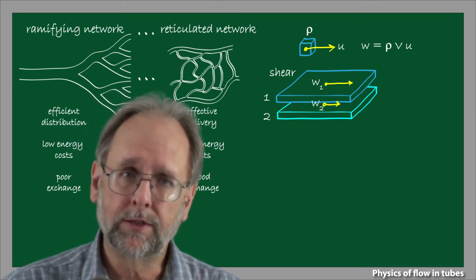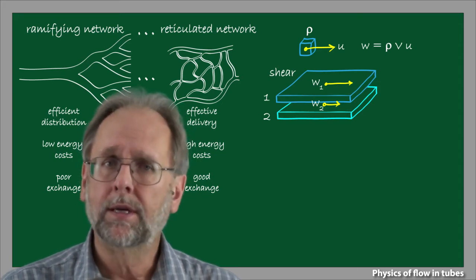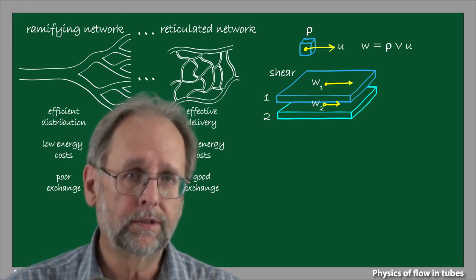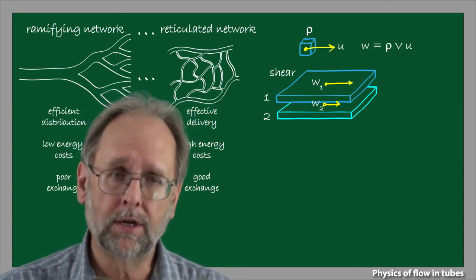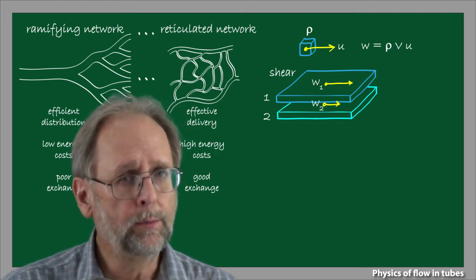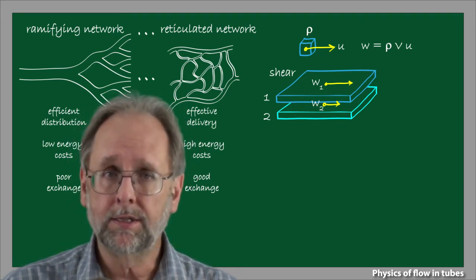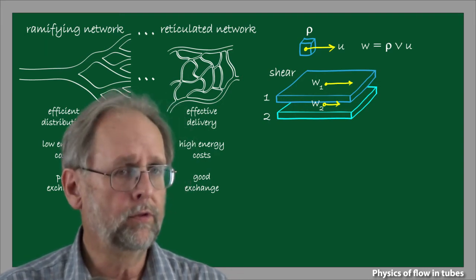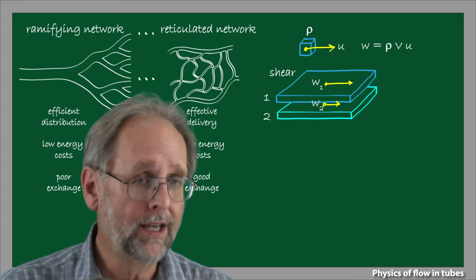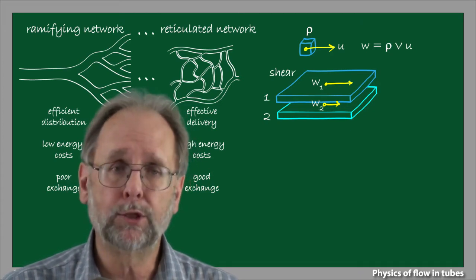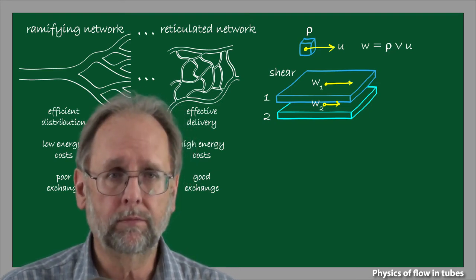The greater the rate this transfer of momentum is, the higher will be the fluid's viscosity. You can think about this in terms of the analogy of fluid friction. Higher frictional forces mean higher transfers of momentum, which means higher viscosity. The second point is that fluids can have momentum, but they may not necessarily exhibit viscosity. You can find tables of fluid viscosity in places like the Handbook of Chemistry and Physics, but this does not make viscosity a fundamental property of the fluid, like its mass would be. Viscosity only arises when fluids are subject to shearing motion.